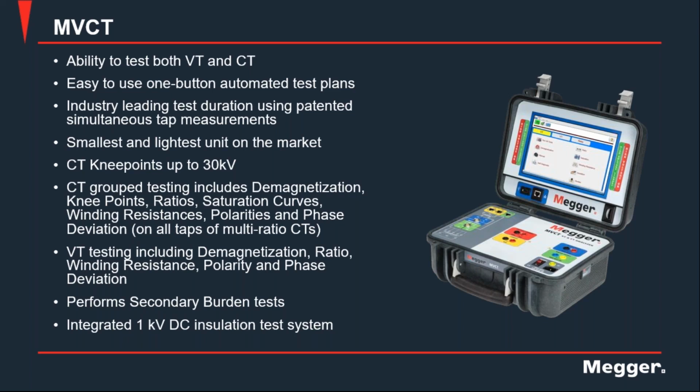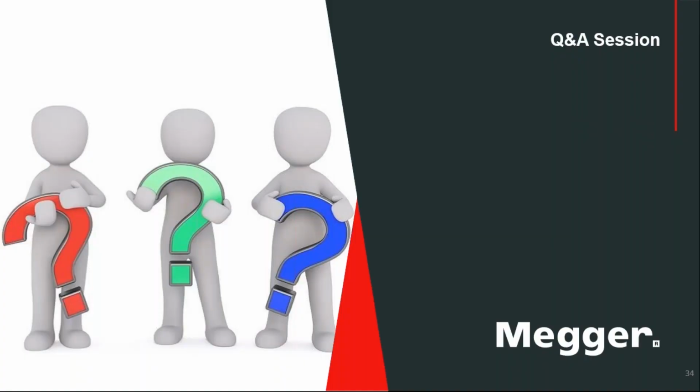And it provides the same features as the MRCT, with the only exception that you cannot test CVTs with this one. You have to use higher voltage for CVTs, and so this instrument won't apply, but you can still test the insulation resistance. You can also test burden and do all the other tests, and it will perform the same assessment on all of the instrument transformers that it can test.